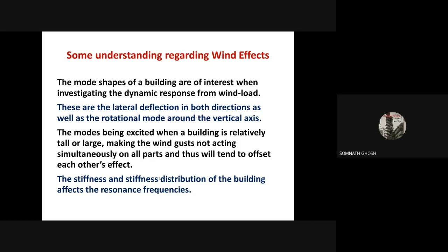Now you see the modes being excited. When a building is relatively tall and large, wind gusts obviously do not act simultaneously on all parts, and thus will tend to offset each other. This you have to understand. The stiffness and stiffness distribution of a building affects the resonance frequency. Remember this. Because when I discuss in detail, you will slowly find that these are the major aspects.